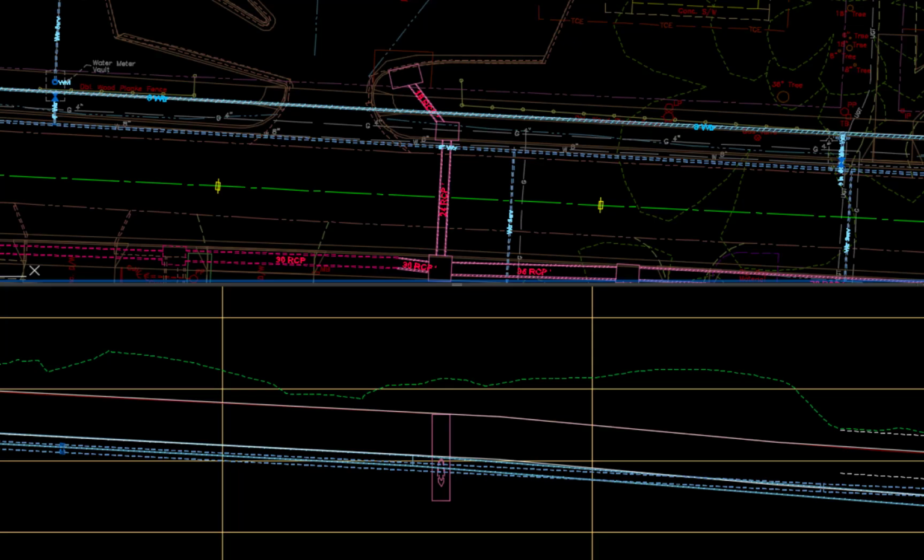Each water pipe crossing with a storm or sewer pipe needs to be analyzed for a possible conflict and what measures should be taken to resolve such conflict. Water pipe can easily be deflected around other pipe, but it is difficult to deflect storm or sewer pipe. In any water pipe vertical deflection, the pipe slope to prevent crests should be kept in mind.